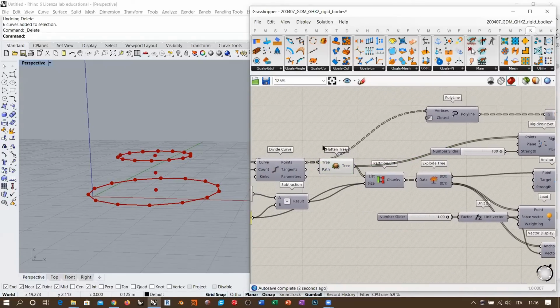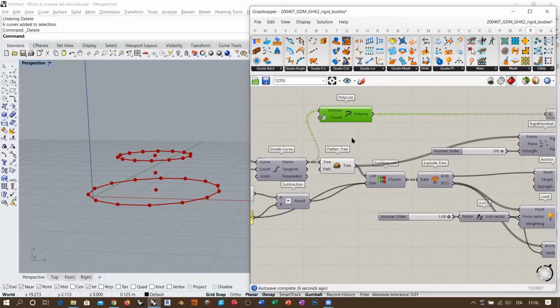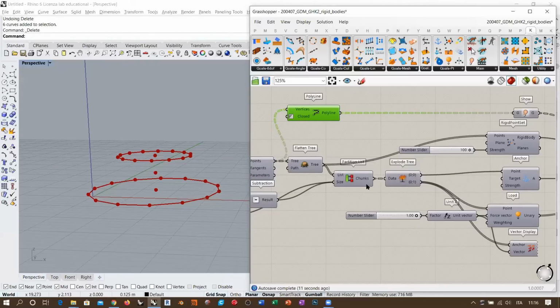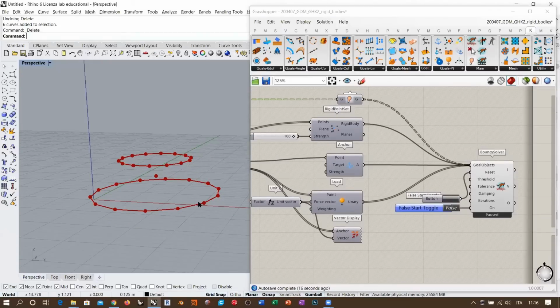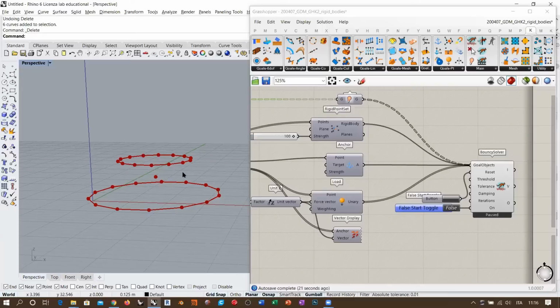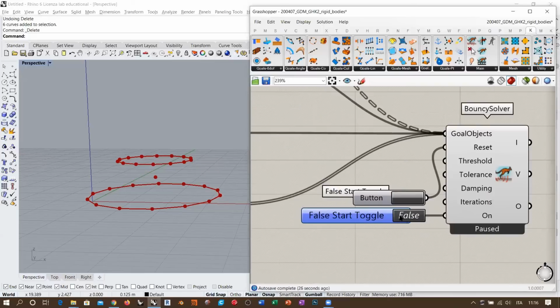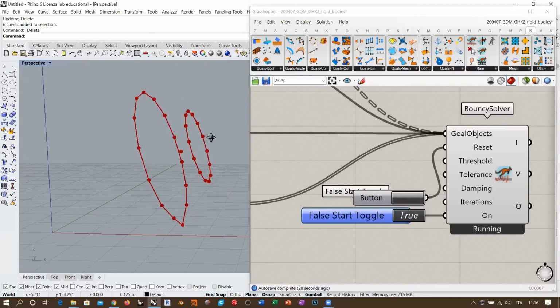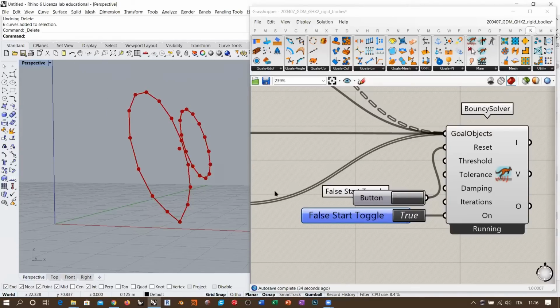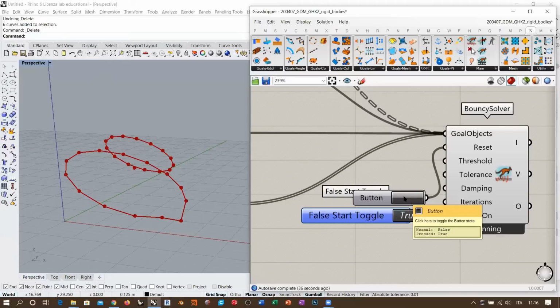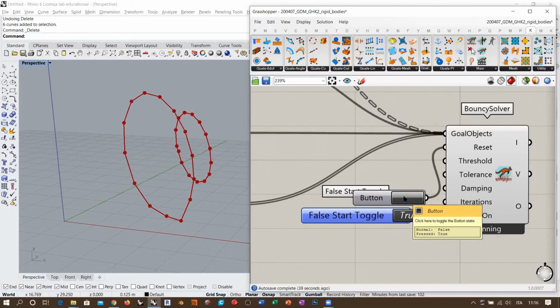So it's just a trick in order to allow using both the polyline and also creating this kind of data manipulation properly. Okay, so I reset this, and what I should have right now is an anchor point here and all these sets of points capable of moving up and behaving like a rigid truncated cone, basically. If I release the simulation, you see that this second circle is being maintained rigidly connected to the first one. So we have two separate bodies acting like one single set of rigid points.